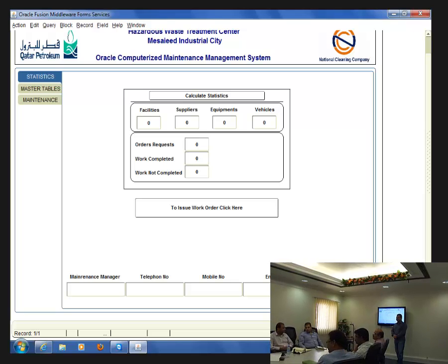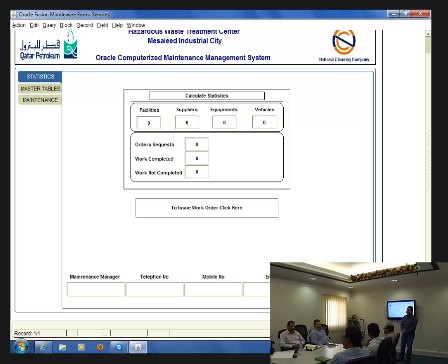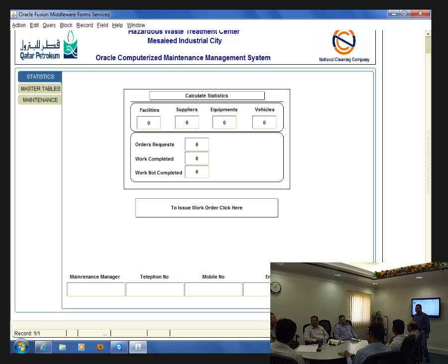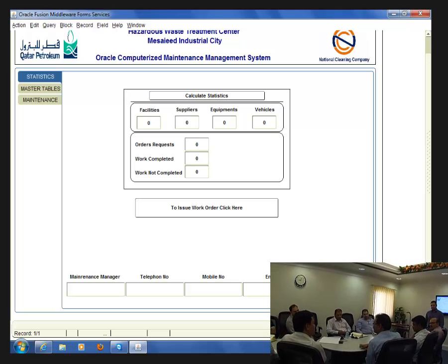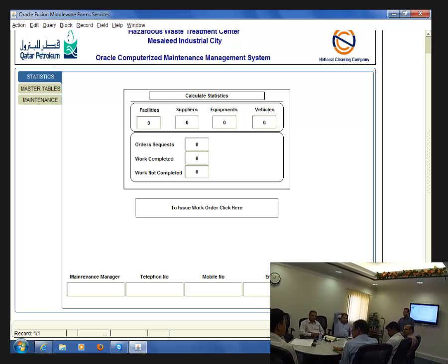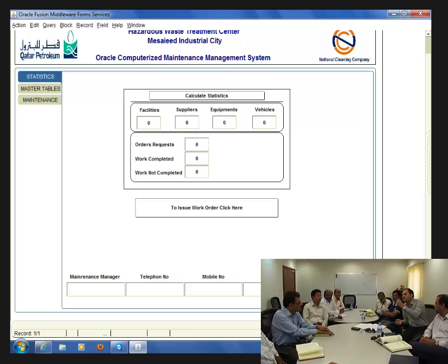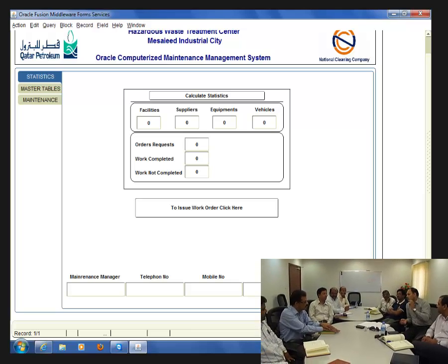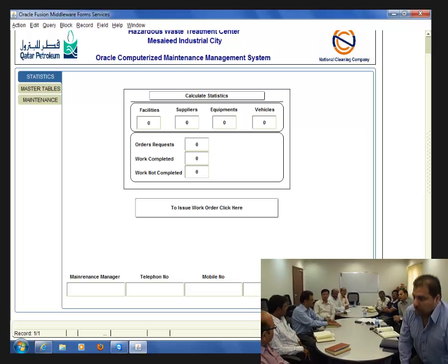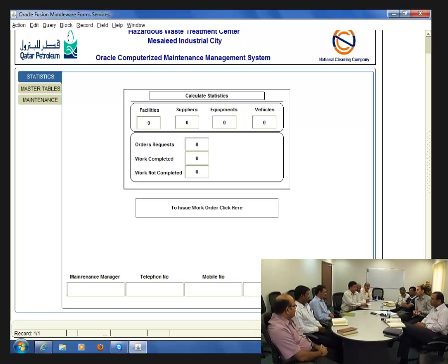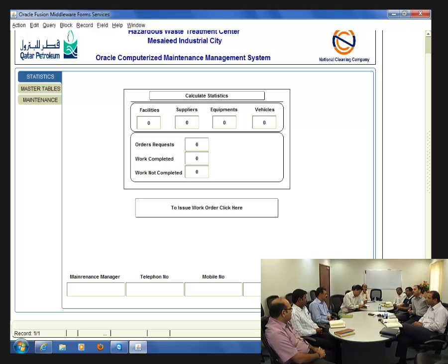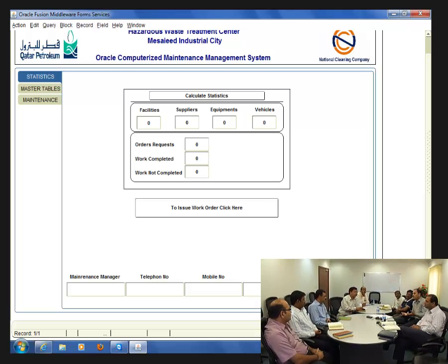We can take the comments from others. Because throughout the presentation I kept on checking, I told that work permit, if it is a hard work permit, high risk work. Wherever you feel that it's a high risk work, like entry into the vessel or any of the storage tank, it's a confined space.